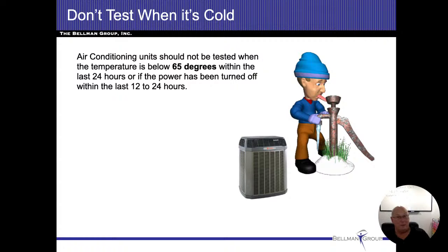So you might go to a house, you're inspecting the home, and then you look at the air conditioner, and it might be just fine. But you turn that air conditioner on, and the refrigerant inside that compressor, around that compressor, is a liquid. Now you're going to be pushing that liquid through the compressor, and that's just going to damage the scroll coils and everything else. So we don't want to take that chance. We don't want to damage the compressor whatsoever.